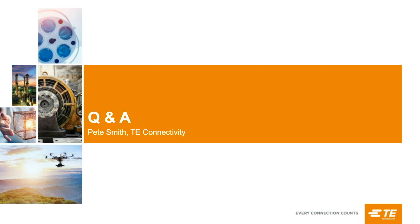We even make one pressure sensor. It's not a very high pressure sensor. It's a low pressure sensor, but it's used in sewage treatment plants. It's a pressure sensor to measure the depth of sewage ponds. And so it literally has a long cable on it. You go out into the middle of the sewage pond and you drop it in, and it sinks to the bottom. And by monitoring the pressure at the bottom of the sewage pond, we can tell you how deep the liquid is in the pond.